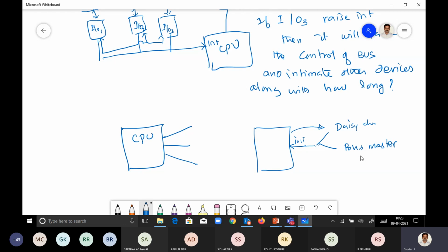So we discussed in detail what an interrupt is and why we need an interrupt, because programmed IO is a low-efficiency approach, so we go for the interrupt concept. Interrupt is high efficiency, but it requires some extra thing in the form of software or hardware to tackle issues. But interrupt is better than programmed IO from a utilization point of view. We are utilizing the CPU much better compared to normal programmed IO.